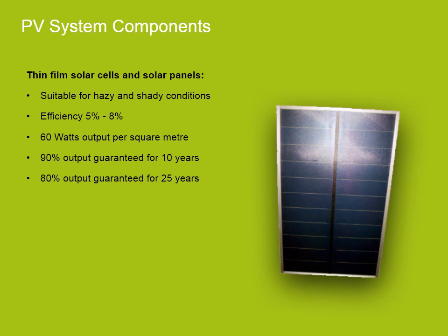Amorphous or thin film silicon cells are made up of silicon atoms in a thin layer rather than a crystal structure. They can absorb light more readily than crystalline silicon, so the cells can be thinner and they use the least amount of silicon. While generally less efficient, there have been technological advancements, meaning some panels can now generate efficiency up to nearly 12%. They offer the best shade tolerance of any solar technology and perform better under hotter conditions.